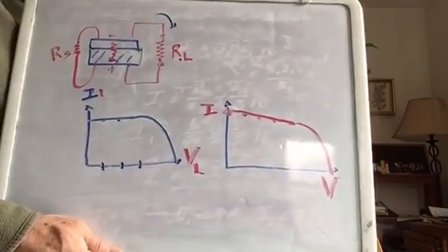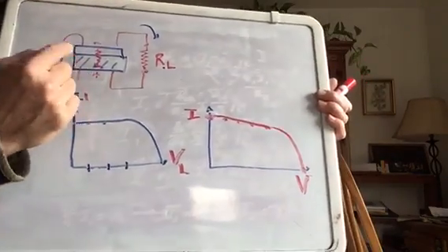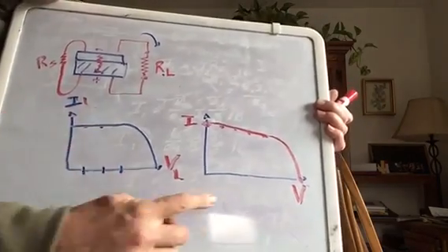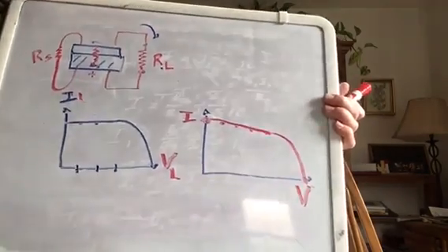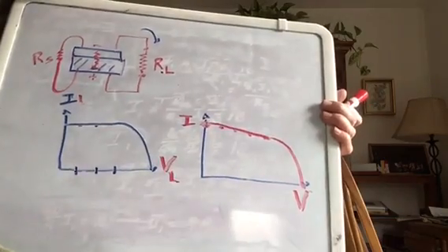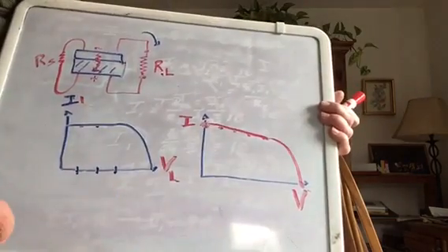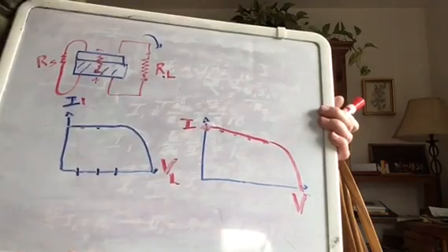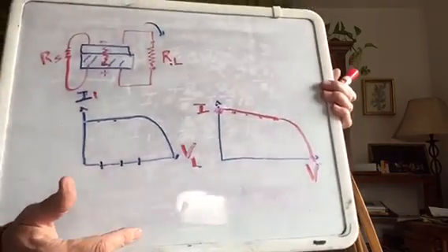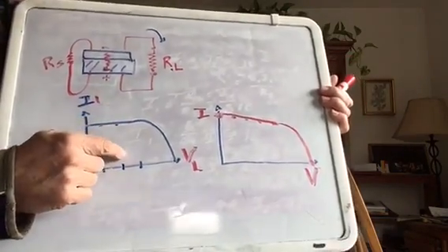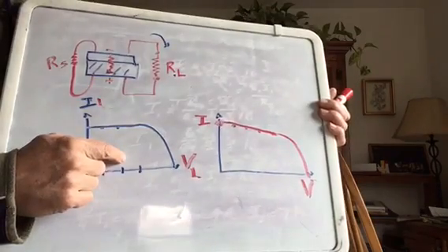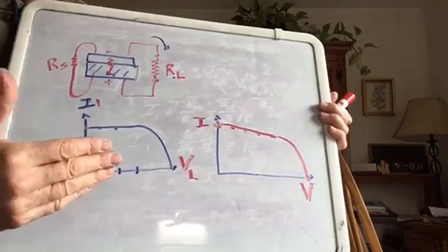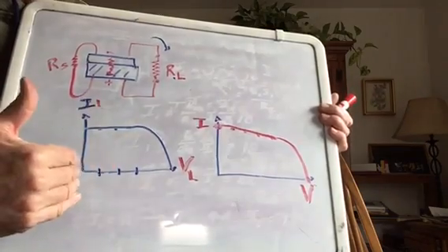We're going to imagine that we have some specs for a PV cell, a PV generator, and the specs say, look, at full sun, the open circuit voltage is 20 volts, and the short circuit current is 2 amps. And that's at full sun, which is 1,000 watts per meter squared. So I just want you to go ahead and graph it more the way that the manufacturers give those. So we're going to try to do a graph like that. Once again, VOC, 20 volts, ISC, 2 amps.